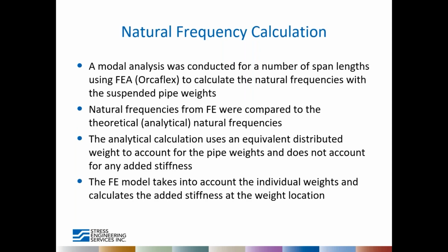So to investigate that, we did a modal analysis for a large number of span lengths using finite element analysis. In this case, we used OrcaFlex to calculate the natural frequencies with and without the suspended weights on the pipe. And we also calculated the natural frequencies using beam theory and analytical methods. In the analytical method, we distributed the weights into the weight of the pipe. So there were no point loads, it was just distributed along the pipe. And the theoretical calculation doesn't take into account any added stiffness from the weights.